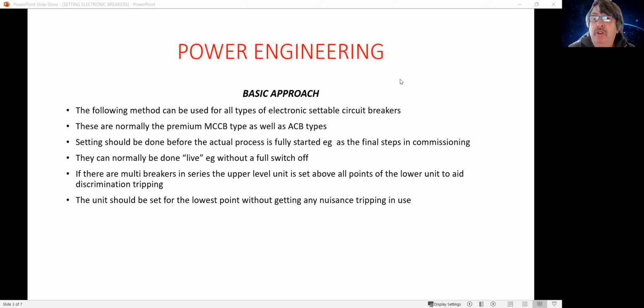The setting should take place somewhere before the final commissioning and livening up takes place. So these things can be done off drawings, if you have consultants that take the drawings and give you the values as a manufacturer from a panel board, and say the following breakers are what I'm recommending for the site, and you preset them at this when they arrive on site. So that's something you can do in a workshop.